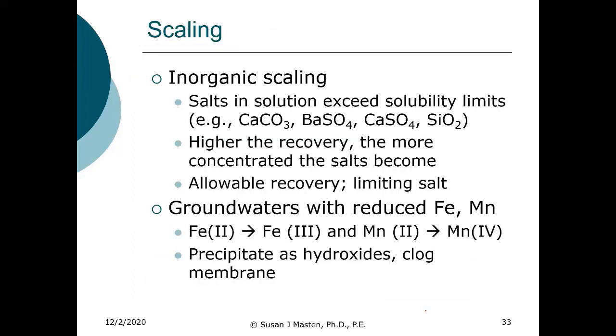We can also have scaling. This is different than fouling. This really is the result of exceeding the solubility limit. So here is our membrane surface. Water's flowing through that membrane surface. We have a concentrate on this side, so the water's becoming more concentrated.